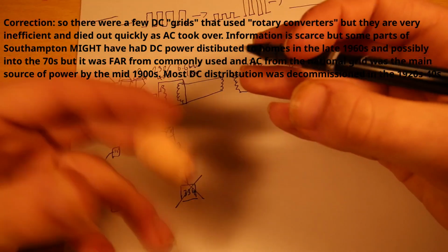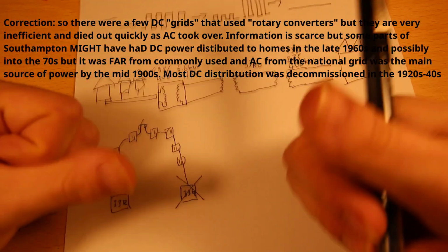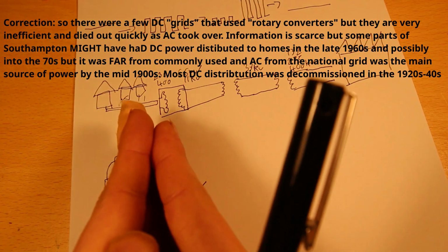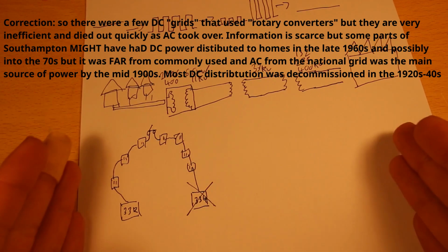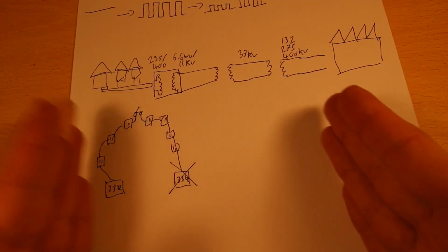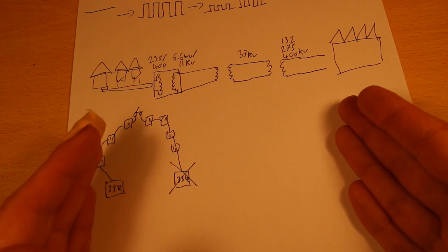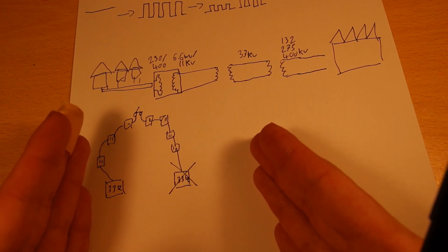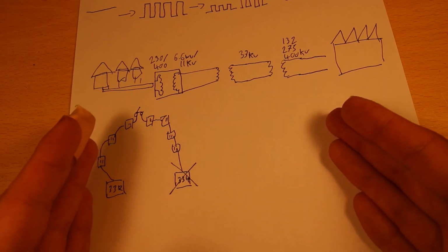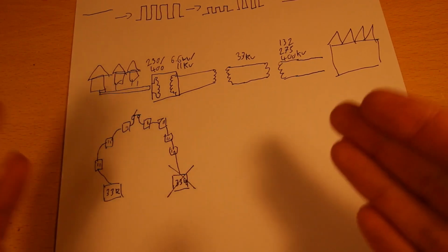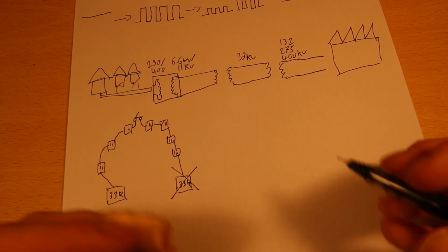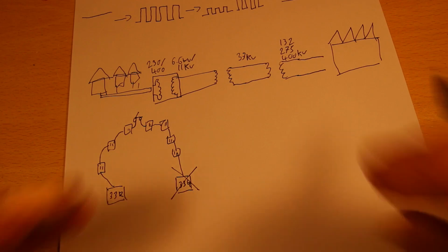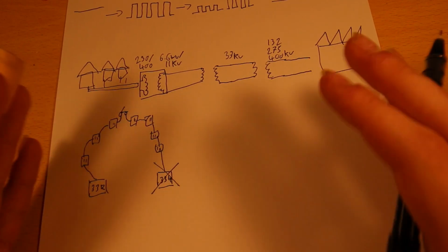So somebody decided, I know, why don't we step the voltage up, make it much higher, and then if we're going across a cable and we are dropping 100 volt across a cable run, if it was 240 volt, we've dropped almost half the voltage. But if we make that voltage, say, 33,000 volt, 100 volt of volt drop, that's nothing. We can ignore that. So when we then step it down, it's more efficient. That is the key that allows the grid to function.